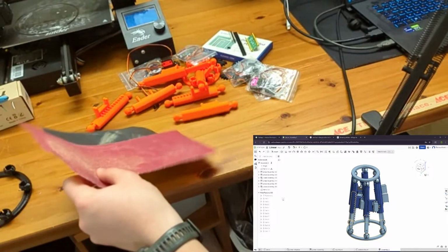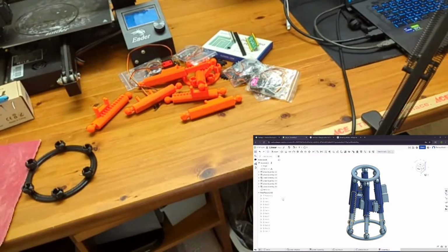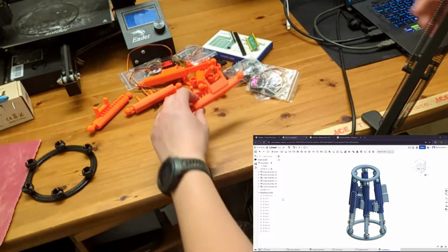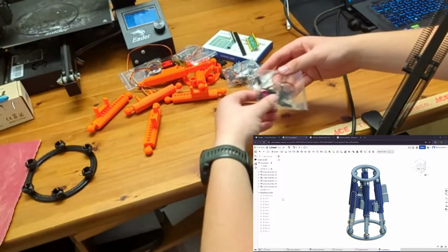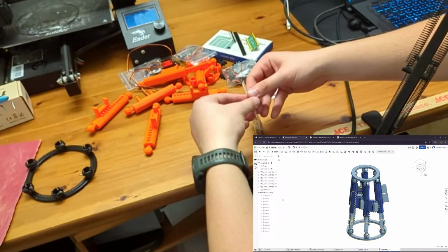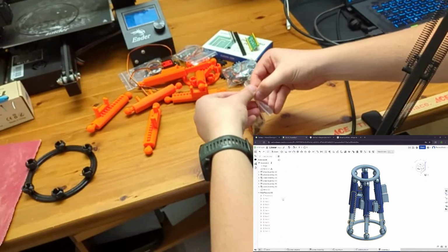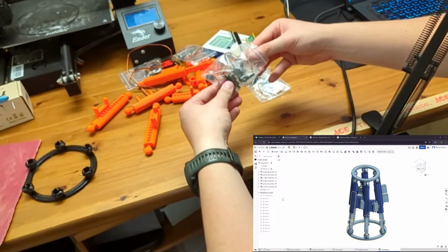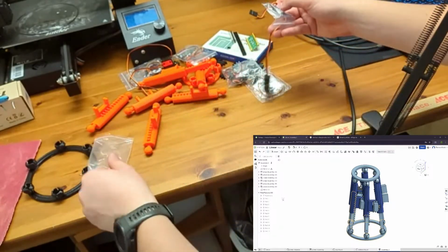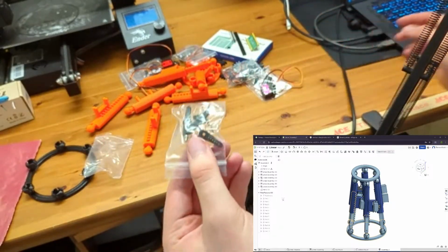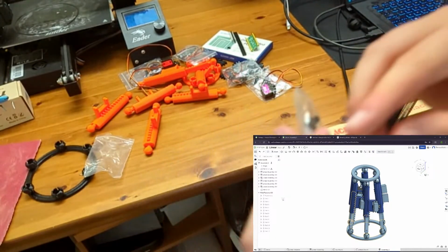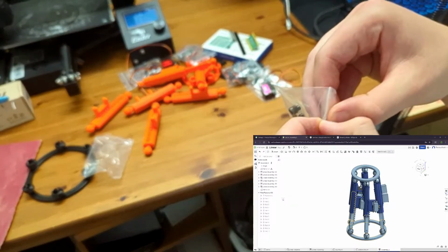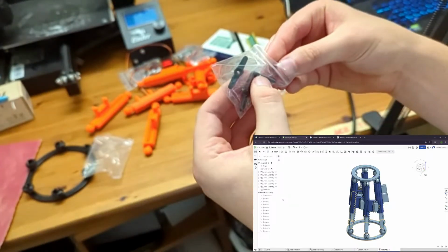Okay. So next up, we've built the rack and pinion gears and their holders. What's next, I believe, is going to be attaching the pinion gears to the servos. Now, a lot of people on the internet will say you have to use these servo horns when using a servo, because a 3D print is never going to be strong enough or precise enough to hold these little servo arms.